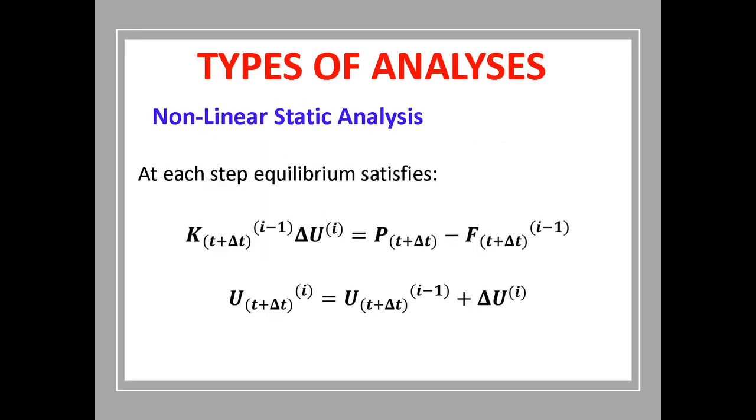Nonlinear static analysis is undertaken iteratively in time steps. In this case, the stiffness matrix is not constant but dependent on the state of stress and the constitutive model relating the stresses to strains. Therefore, the stiffness matrix is the tangential matrix used in each iteration of the solution of the nonlinear problem and changes with each iteration at each time step.